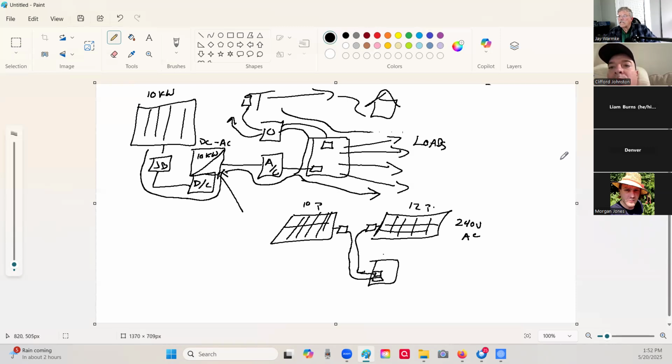This is designed to handle up to 80 amps of input. Now, the proprietary cable from Enphase is limited to 20 amps. So this wire here has a maximum of 20 amps, which just happens to be 13 microinverters. So I could go with one here and one here.